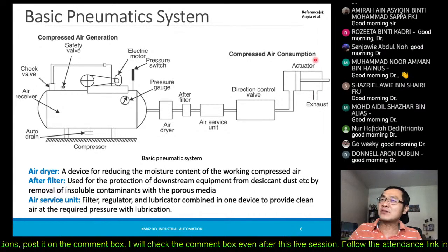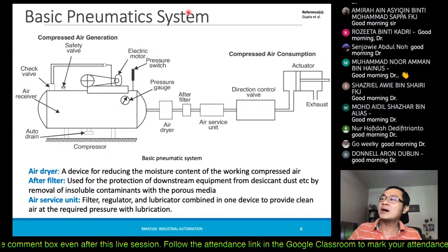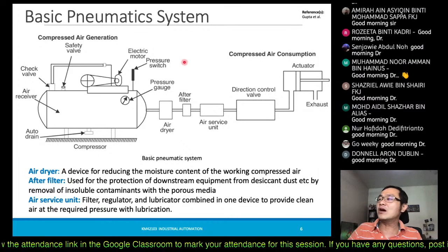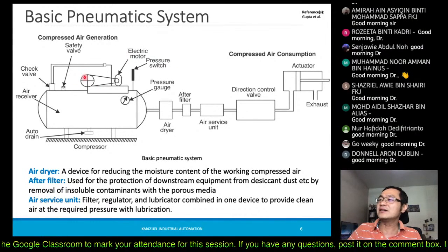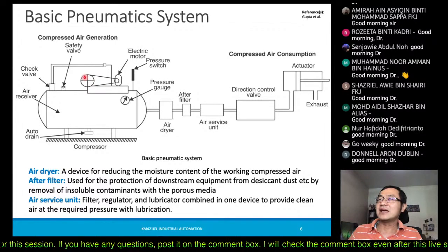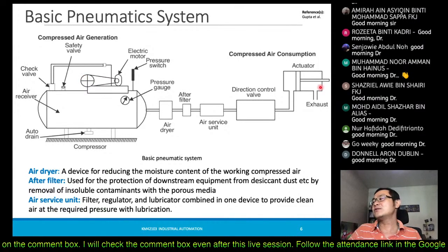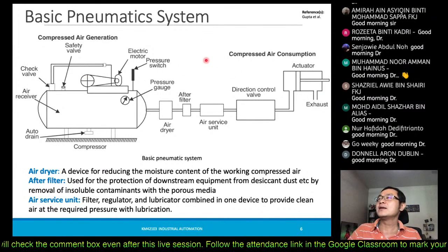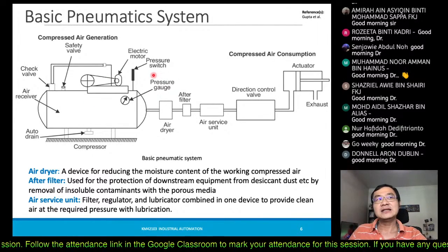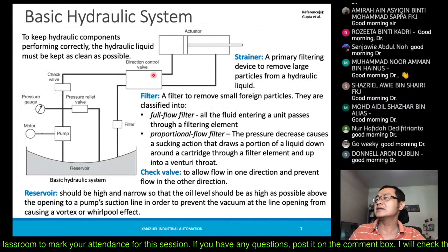Then that part, we may want to reconnect to a lower pressure tank, to save the power of keeping compressing the air from the atmospheric pressure to the high pressure that you want. So when we release it to a lower pressure tank, it will help to reduce the energy required to compress to the higher pressure.